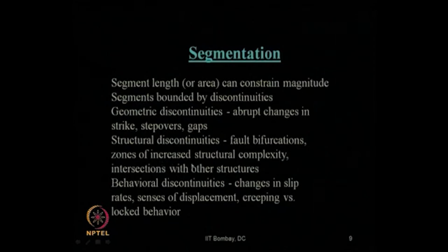Zones of increased structural complexity, intersections with other structures, behavioral discontinuities, changes in slip rates, senses of displacement, and creeping versus locked behavior. So, all these characteristics or properties need to be considered when we are trying to identify a segment, an earthquake segment. Clear?